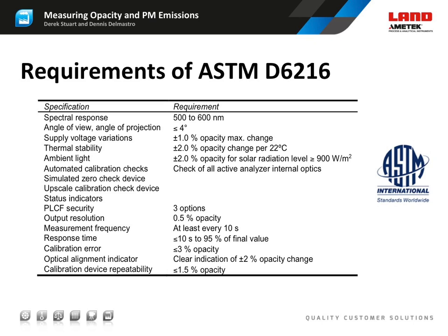Manufacturers had to adhere to these specifications and requirements as well as prove that their design could meet them. These design and performance specifications were comprehensive and extensive, but eventually improved the overall performance of opacity monitors in the market. These were known as ASTM D6216 Design and Performance Specification. This slide certainly is busy, but it gives the basic design and performance specifications that opacity monitors must meet.